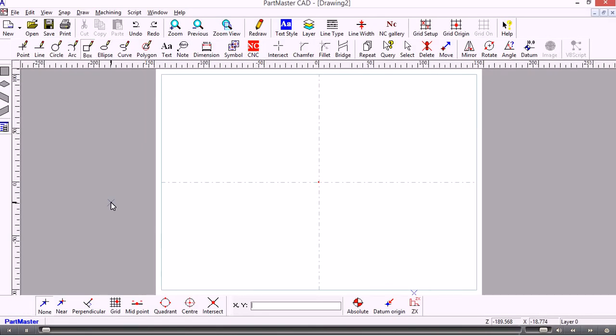Following on from the previous typed input video, we'll show you now how we can draw some lines. I'm still in the CAD system. I've started a new drawing, so I'll go into line mode, and the option I'm going to choose is a normal line. What that needs is a start point and then a subsequent end point for the line. So it's like creating a chained line which needs the start and the end.